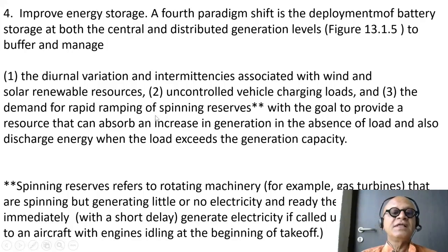availability, right? The demand for rapid ramping up of spinning reserves. There are places where the gas turbines keep spinning, not producing electricity, but when the demand goes up, they will have to start producing energy to meet the loads. Okay, so with a goal to provide resources that can absorb an increase in generation in the absence of load and discharge energy when the load exceeds the generating capacity.